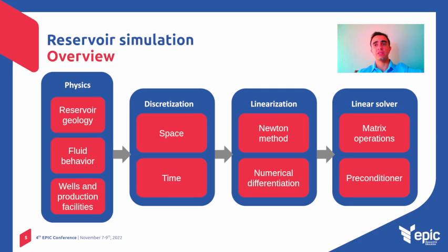And as these relations are complex, this discretization will result in nonlinear discrete equations, so they must be linearized. And this is done via Newton-like methods and numerical differentiation, which later has to be solved with linear solvers, which involve matrix operations and preconditioners.